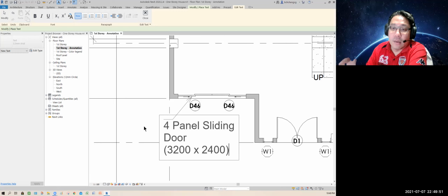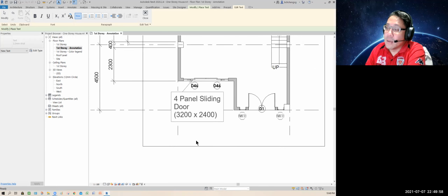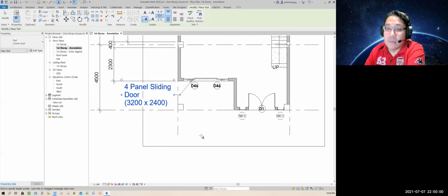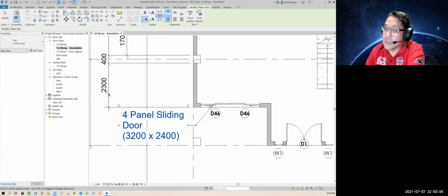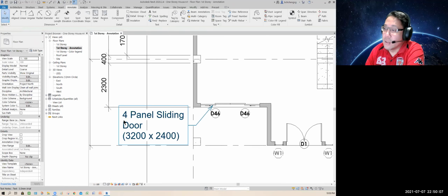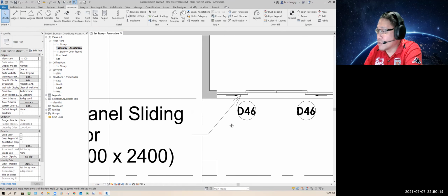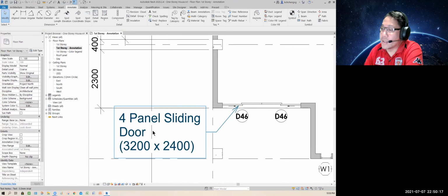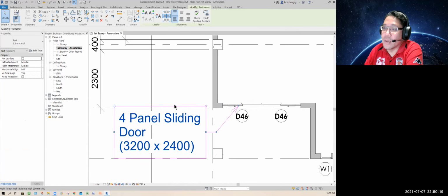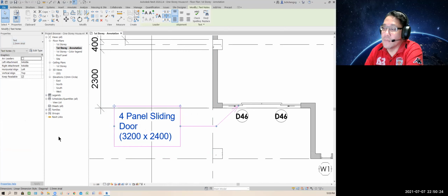Okay. So when done, remember, Revit using text or score text. Don't keep pressing enter. Just pick outside. Then it's done. Okay. But there's something here that I'd like to change. See, my text 2.5. This guy looks very big, and the arrow is like a skeleton arrow. So change it. Select the text itself from here. Text height is here. Change to 2.5.